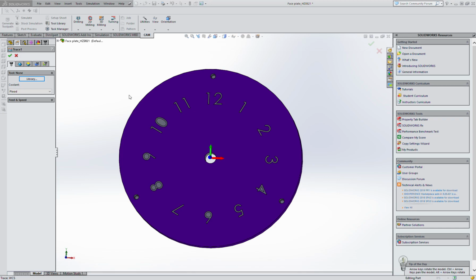If you click here, you can see on the right there are many different tools listed. There are drills, and if you scroll down, you can see flat end mill, ball end mill, bullnose end mill, chamfering. We're going to choose the 1/8 ball end mill, and select.